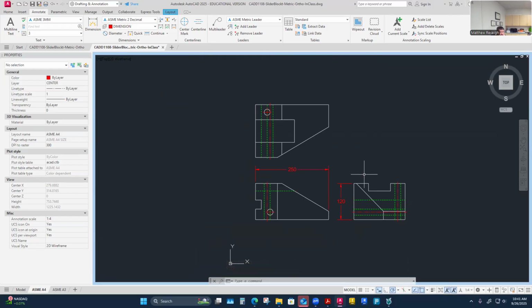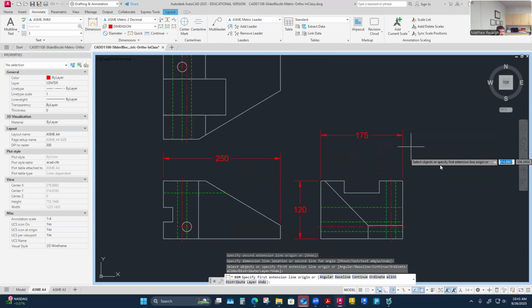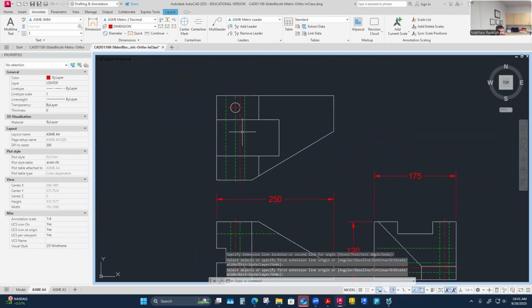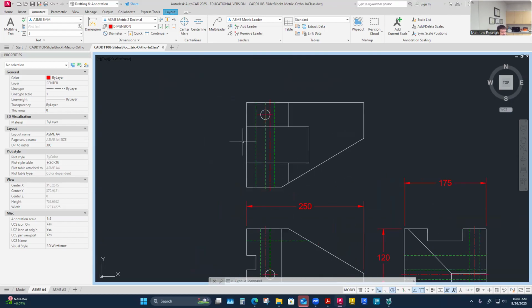And then the last overall dimension I need is definitely the depth. And so I feel like I will probably choose this one as my overall depth up here somewhere. I feel like I'm also going to take care of the notch dimensions in this view. That's where they, or I could in the top too. So tomato, tomato, but over here, maybe it's a little better because I feel like I'm going to have room and it kind of is the in-between view rather than detailing the top notch over here. Just wouldn't be wrong. It would be the difference of a good or better practice. But definitely not bad to have done it.